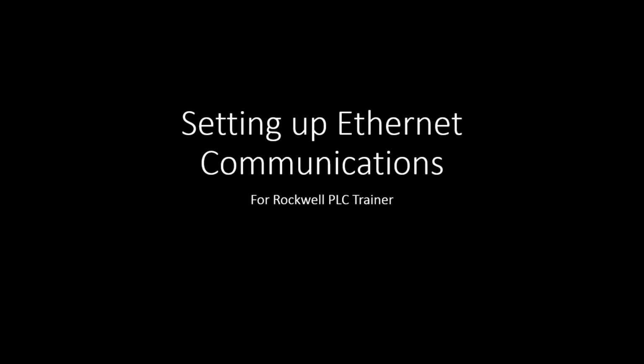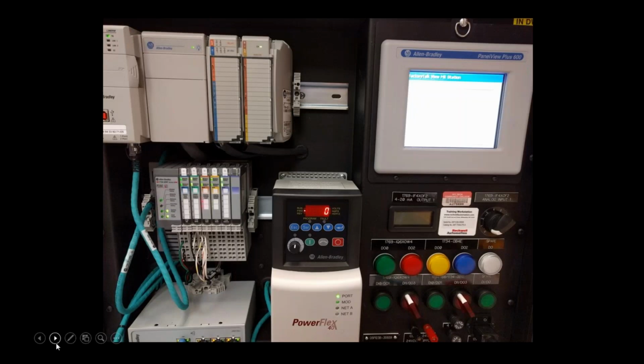This is the trainer that we have. Let me move forward. It looks like it's a fairly simple setup with the control logics. You can see the PLC connected by Ethernet. Here's a network switch. Here's the distributed I/O, the PowerFlex, our operator panel, and an HMI. And then an analog output and analog input. Everything is connected through the switch. How we set up communications is everything is run by Ethernet to this switch here.